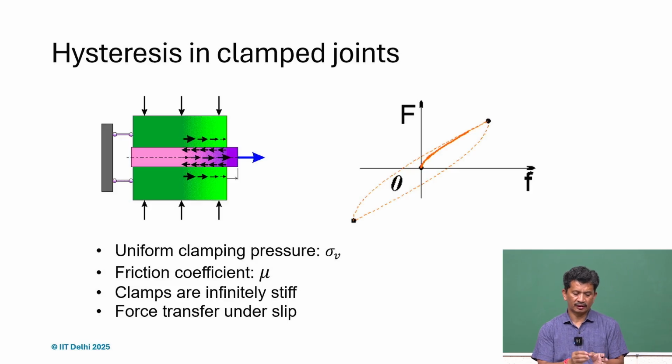Nevertheless, even if there is no apparent motion, there can still be hysteresis, and that happens because of the microslip. So we don't see it, but because of the nature of the joints, we encounter hysteresis, and the moment we have hysteresis, we'll have a positioning accuracy problem.